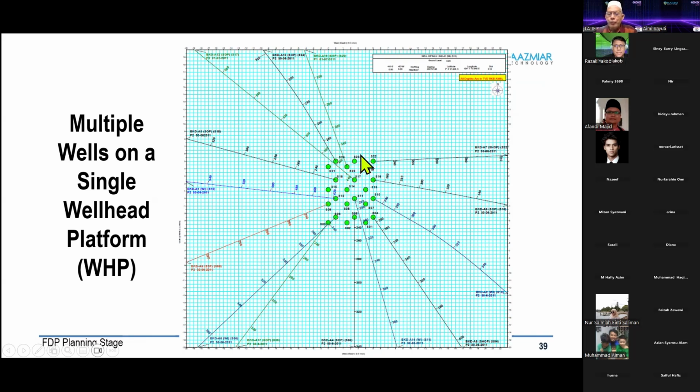For drilling, because it's offshore, we want to have one drilling center that can manage 20 wells, going to each target. So if the reservoir is shallow, that means you're going to have a high angle to each reservoir. So it might be difficult. We have to think about drilling a high angle well, which has another complexity, another difficulties. So there'll be some additional cost there. But if you have a deeper reservoir, then your inclination will be much less than, let's say, 50 degrees. Then it's much more convenient to drill. And then, of course, the drilling will be faster, less problematic, and so on.